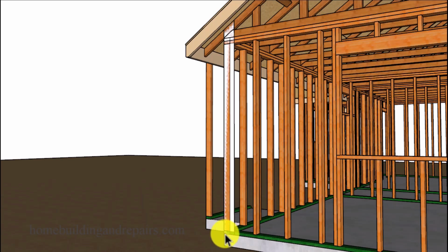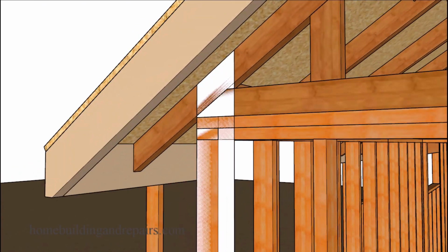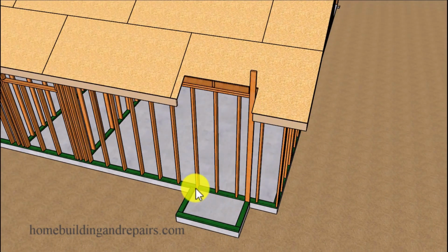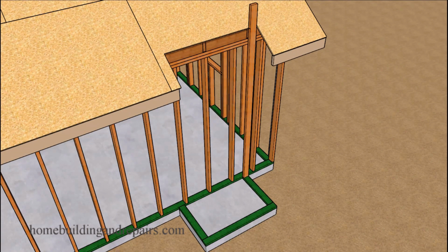So with that said, let's take a look at a measurement you could take from either the top of the building foundation or the top of the wall framing plate to the bottom of the sheathing, and then add for the thickness of the sheathing as one way to get a starter measurement. However, I don't think that's going to be necessary because you can measure from the top of the bottom framing plate to here, and then do some simple math to calculate the rest of the wall framing chimney stud.